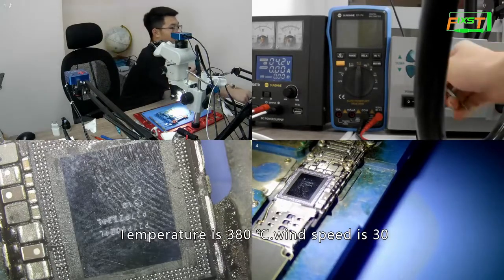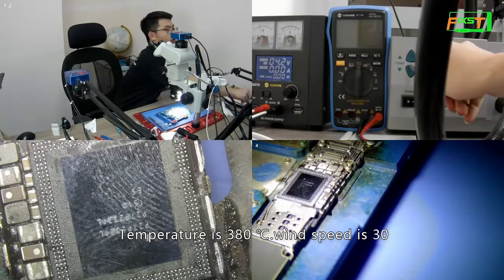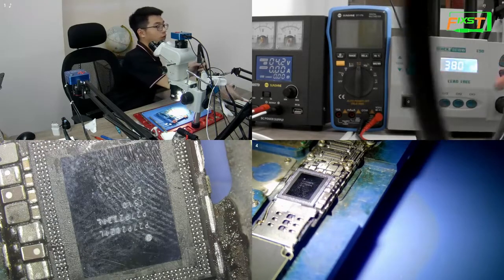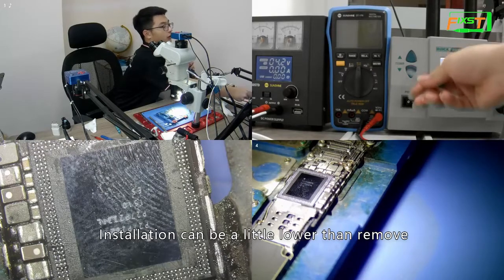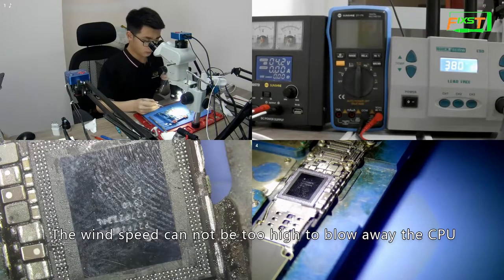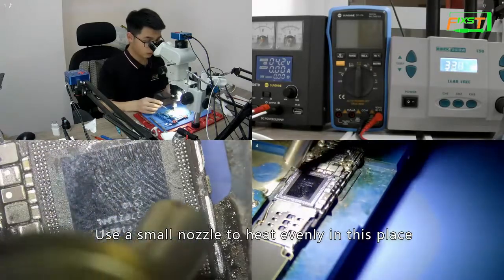Temperature is 380, wind speed 30. Installation can be a little lower than removal. The wind speed cannot be too high, or it will blow away the CPU. Use a small nozzle to heat this place evenly.